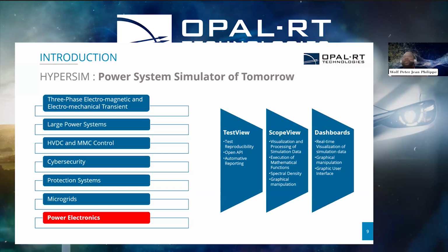Some of the things that are integrated with HYPERSIM: we have TestView. Basically, TestView allows you to run a Python script to run multiple scenarios without doing them one by one. You can run the Python script and run the scenarios and get your result later. Or you can even use TestView to do automatic reporting, plotting your data, analyzing your data, and so on.